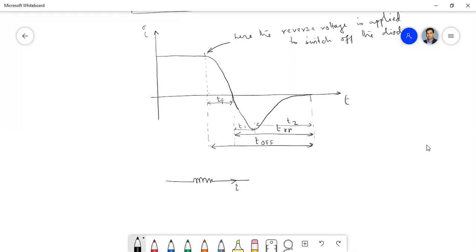If the current is a steady DC current, there will be no voltage drop. But if the current is alternating, or if there is any change in current, then there will be a voltage drop in the opposing direction, and that voltage drop is defined by L di/dt. That you know, I think everybody. So everybody understands this point, isn't it?